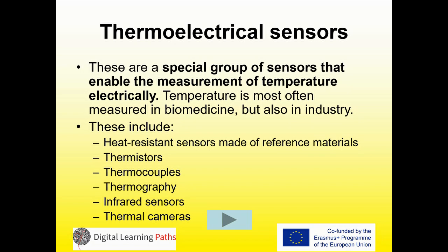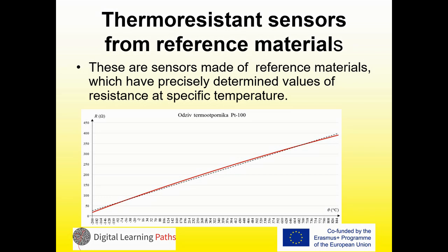Thermoelectrical sensors. These are a special group of sensors that enable the measurement of temperature electrically. Temperature is most often measured in biomedicine but also in industry. These include thermoresistant sensors made of reference materials, thermistors, thermocouples, thermography, infrared sensors, and thermal cameras. Thermoresistant sensors from reference materials. These are sensors made of reference materials, which have precisely determined values of resistance at a specific temperature.